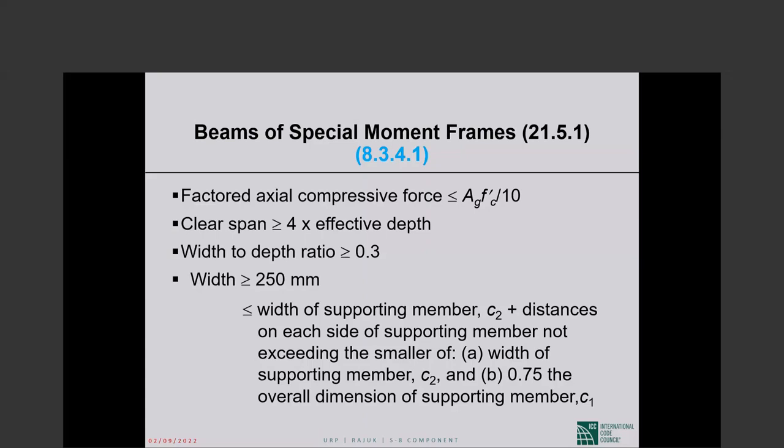And this is where deformation compatibility comes in. This is where 21.13.6 comes in. Are you going to satisfy the deformation compatibility requirement, which is difficult to do? Or we said if you are not going to check, throw in punching shear reinforcement. This is why it is placed in 21.13.6. That is the right section, the gravity frame section.